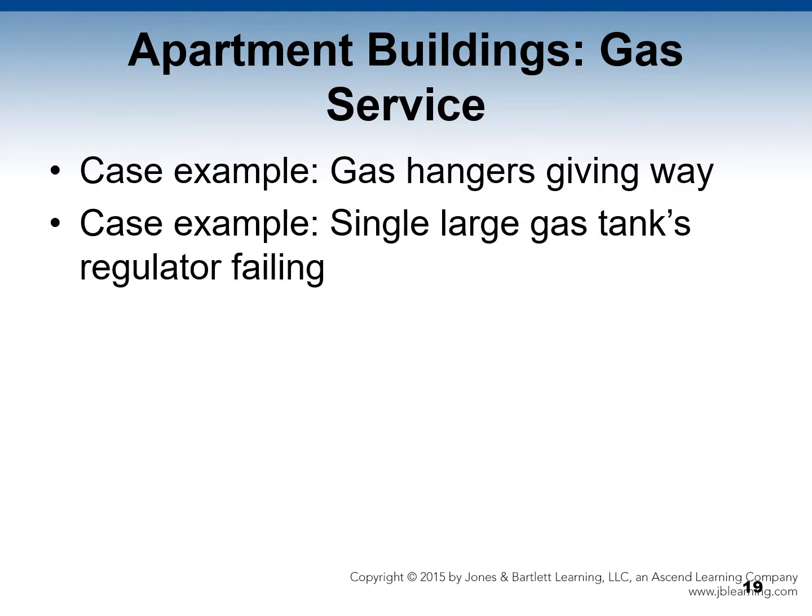One case example is gas lines that were located below the ceiling of a passageway between chicken wire lockers provided to each tenant. Now, you'll see this very often in inner city apartment buildings, definitely in the Midwest and Northeast. You have in the basement these chicken wire lockers. A fire engulfed some of the lockers and one of the hangers gave way. 20 gas pipes overhead fell down to the floor. The pipes failed, gas was released, and another fire was ignited.